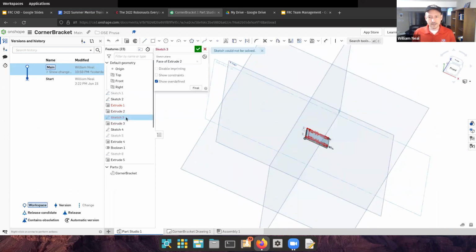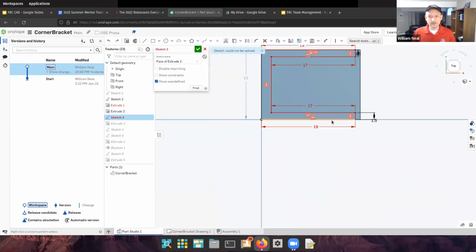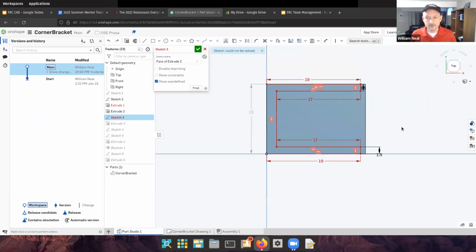Then I made another sketch. And you see here, I can look at the top. And, oh, it looks like there's some errors I have there. It still let me have them. Oh, no, those are just constraints, aren't they? So sorry. Is that an error? Sketch could not be solved. Yes, I have an error in here. So I may have to delete some of these to find out what is being contradictory in here. I could click one and delete it, for example, and continue deleting the constraints until I don't have a contradiction anymore. And so you see, I specified some lines there on that sketch.